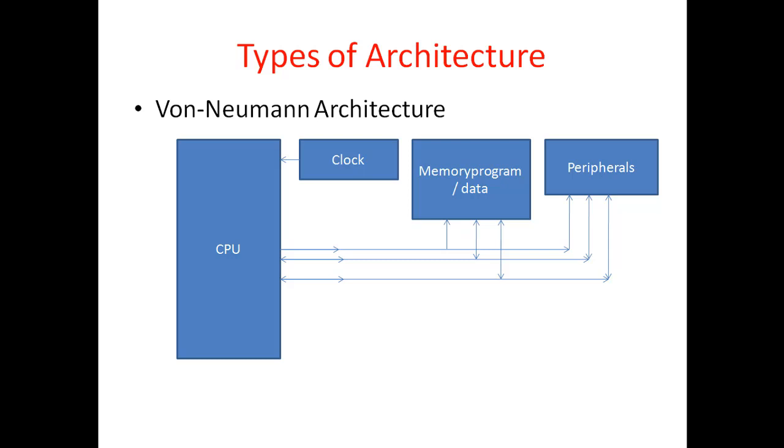The data bus is used to transport data between the CPU and its peripherals. It is bidirectional. The CPU can read or write data in the peripherals. The CPU uses the address bus to indicate which peripheral it wants to access and within the peripheral, which specific registers. The control bus carries signals that are used to manage and synchronize the exchange between the CPU and its peripherals, as well as indicate if the CPU wants to read or write the peripherals.